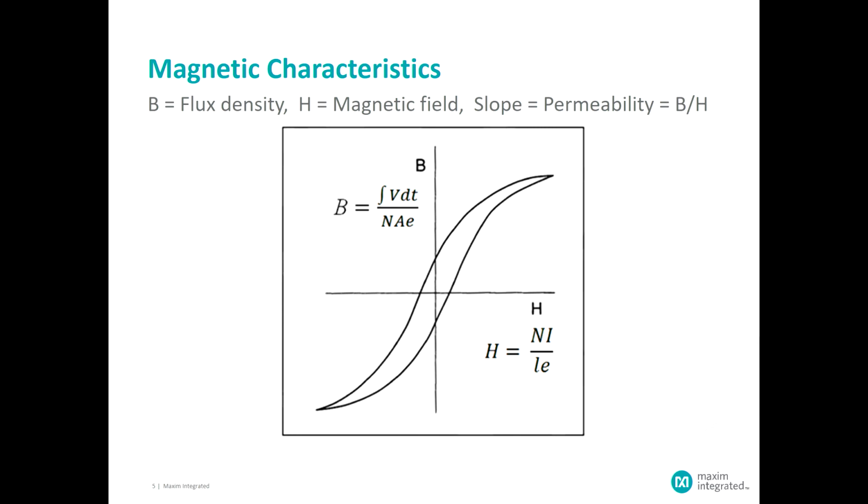One other thing to point out about the curve is that it is not polarity sensitive. You can see that the first quadrant and the third quadrant have exactly the same characteristic. A magnetic device doesn't care which end is the North Pole and which end is the South Pole. It has the same characteristics in both directions. Most of our power supply circuits tend to want to use the excursions in the right-hand quadrant, the upper right, the first quadrant, because we're talking about positive currents and positive voltages, but not all. And so there is the possibility of extending the usage of the curve.